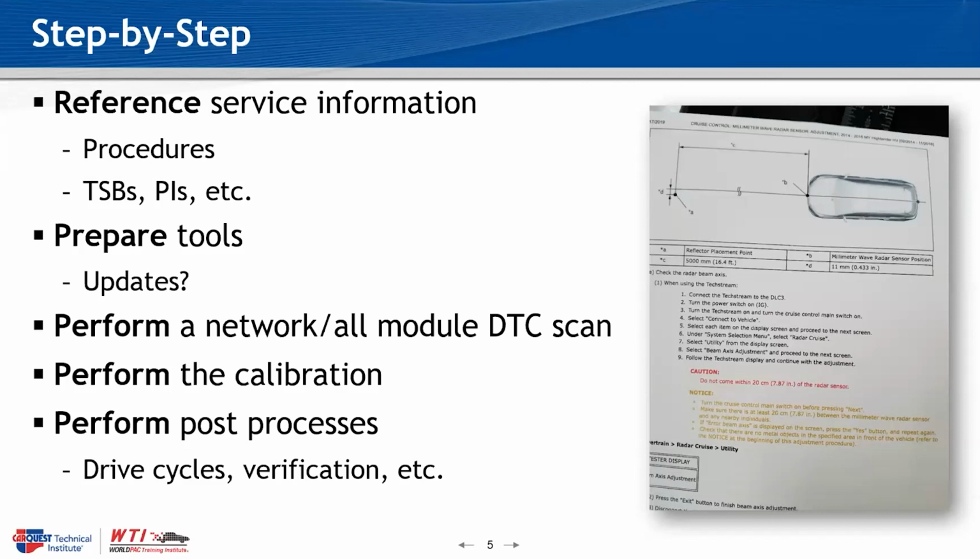At the correct ride height, it has a certain spot in the road that it starts and a certain spot in the road that it stops seeing. Depth of field, if you're a photography guy. If you lift that vehicle and recalibrate that sensor at a more downward angle, you limit that depth of field. So could it see something? Yes. Would it see something at the right time? Probably not. And so that's the concern.